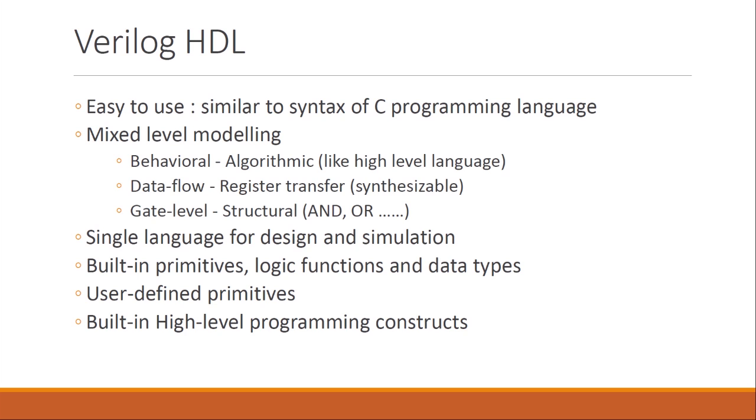There's another way called data flow, and you can also use gate level modeling. In behavioral modeling, it's more like what you see in C: in an algorithmic form, you can describe how the circuit should work. In data flow modeling, you will be describing circuits at the register transfer level.